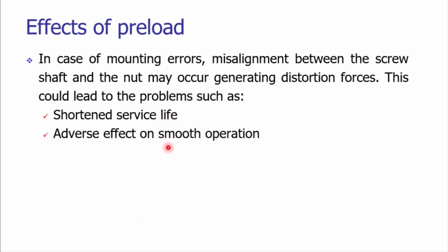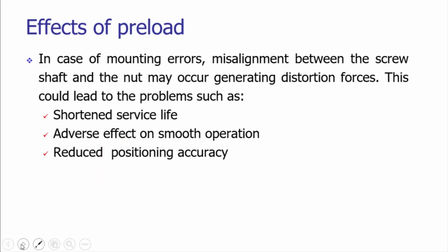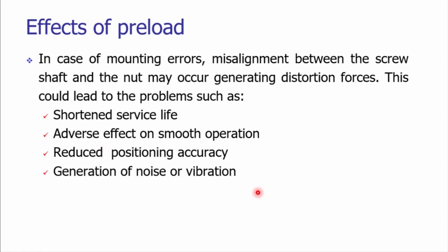It certainly affects the operation. We may not get the smoother operation. The accuracy would be less. There would be reduction in the positioning accuracy. There may be generation of the noise and vibration, and there may even be catastrophic failure of the screw and nut arrangement, that the screw shaft may get broken down.